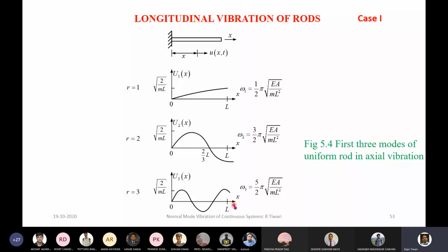So the same beam at third mode will be having three parts, not equal parts, but three parts, and every point will be having a different displacement, and maybe in between they can have different direction of the displacement in positive x direction or negative direction. So this is the analysis or the visualization of the axial vibration, because axial vibration is more difficult to visualize as compared to the bending vibration. So we are talking about the vibration of the beam which is moving axially.